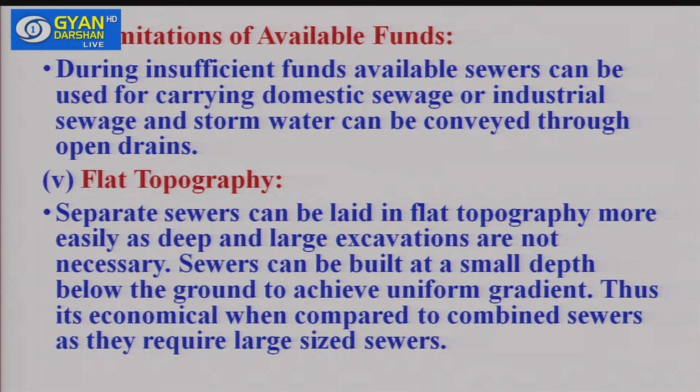Sewers can be built at a small depth below the ground to achieve uniform gradient, and thus it is economical when compared to the combined sewers, as the combined sewer requires large size sewers. So in case of flat topography, it is better to go for the separate sewerage systems. So these are the situations basically.